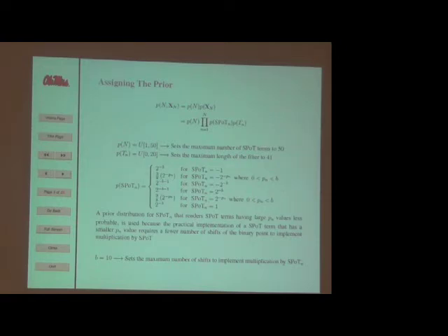So I need to assign the prior parameter to enforce design requirements, or at least design goals and desires. If I set the prior on the number of sine power of 2 terms, I can control that as uniform 0 to 50 in the examples I'm going to show you. The prior on this parameter t sub n, that's the pointer to the taps on the filter, I'm going to set that to 20. This sets the maximum of my filter, and this is something I usually do want to have a hard constraint on.